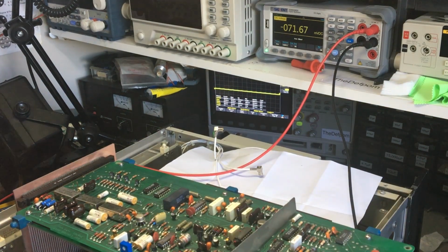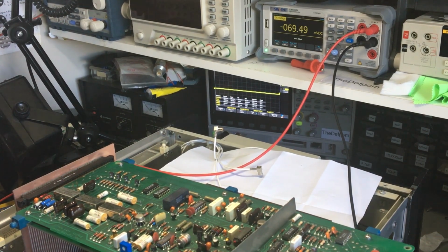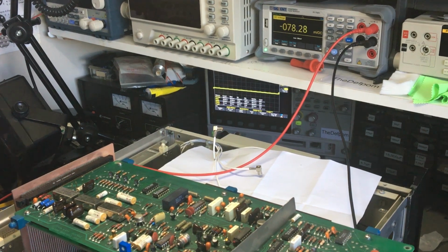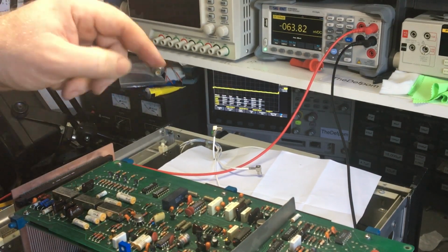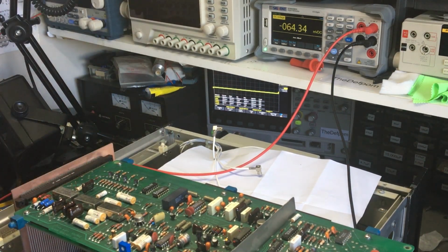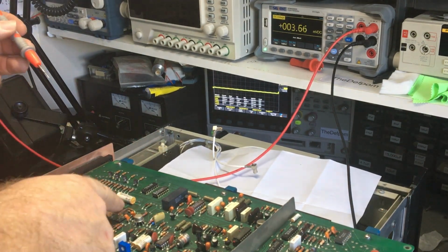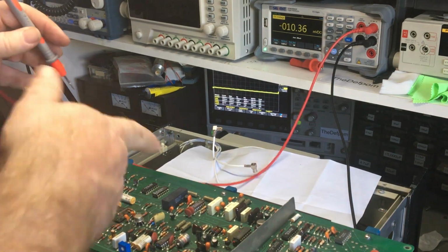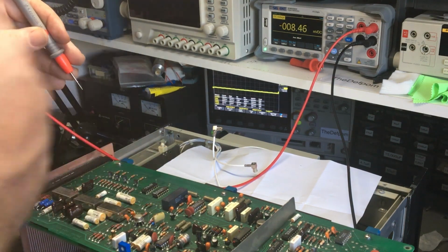Right, so the next one, I've just turned the light on there to try and help the lighting. I just realised it's not particularly the best. So the next one I want to check is U5. This converts the BCD input, which I just checked on this chip as well, into individual lines for switching purposes. This feeds switching transistors, which control these relays. I know the inputs will be there, so I'm just going to go straight to the output and make sure the outputs are switching.